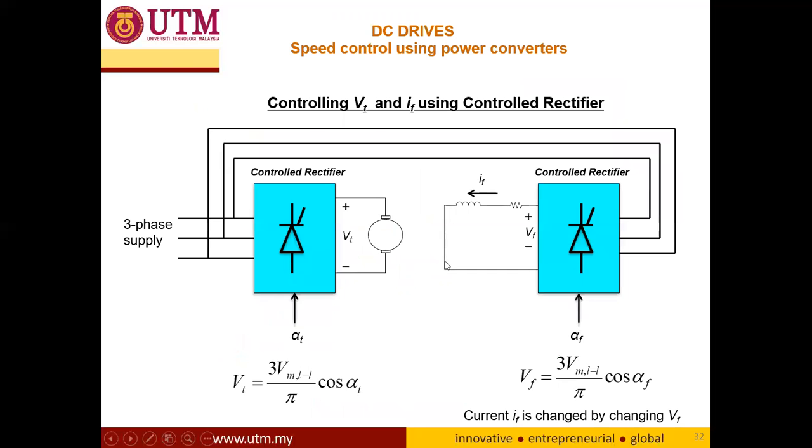So actually, the most efficient way is varying the voltage input, and this is possible by using what we call power electronics. This is the overall system. If you have a three-phase or single-phase AC supply, this system is a three-phase power supply. As you can see, we can have a variable DC voltage at the output by varying the firing angle. So this is the three-phase.